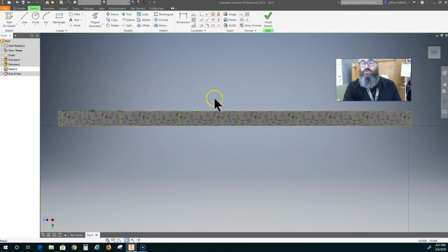And I want to create another line. I'm going to do another offset, and offset these mullions. Now this is where you have to kind of write down some of the dimensions that you're using. So my thickness of this frame was like 0.05. So I want my vertical and my horizontal mullions to be about the same size. So I'm going to do an offset, click on that, and then 0.05. All right, and I'm going to do that to all of them.